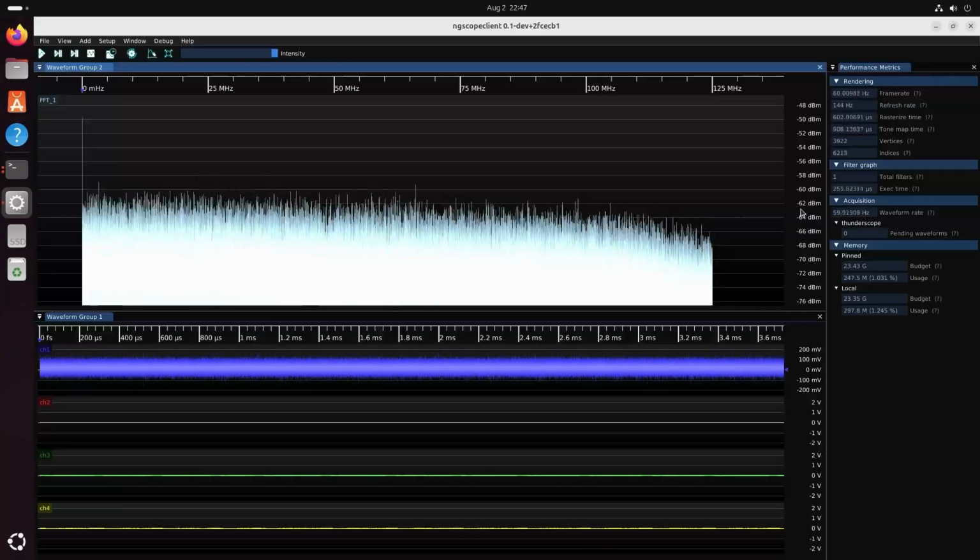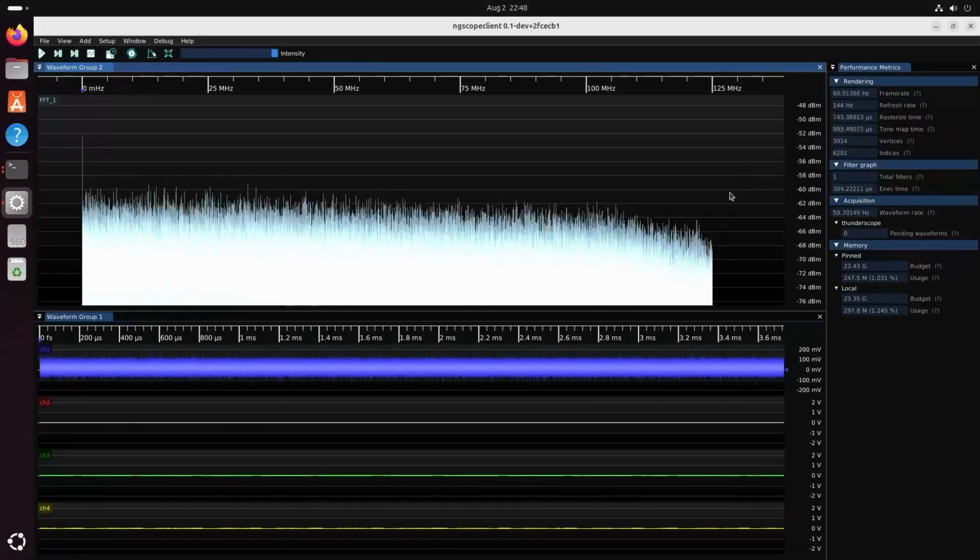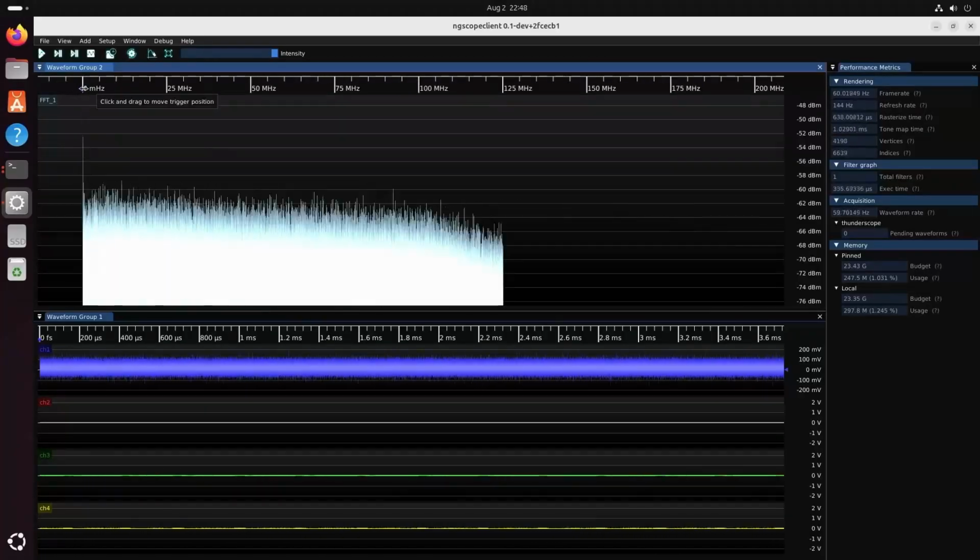So yeah, that's pretty flat. Looks like it really drops off around here. And I, again, suspect that's the function generator giving its rating, which is 125 megahertz, and that's a 3 dB point rating. So probably we're just looking at this region up to 100 megahertz, which looks reasonably flat. Now, this isn't the most accurate measurement.